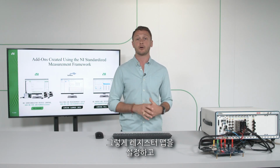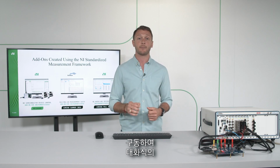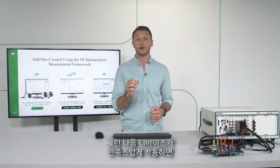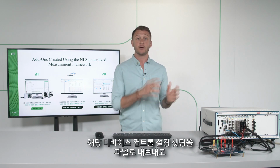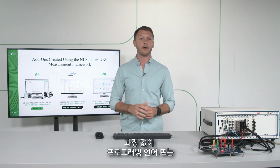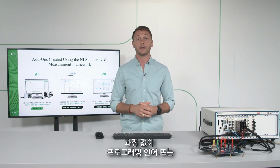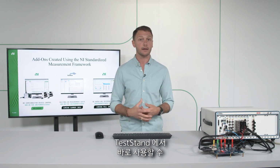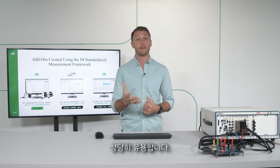So you can configure your register map, power on your part, and do interactive register reads and writes. Then, when you're happy with the way the device is operating, you can export those device control configuration settings to a file and use that directly in a programming language or in TestStand without having to reprogram I2C protocol capabilities. It's really powerful.